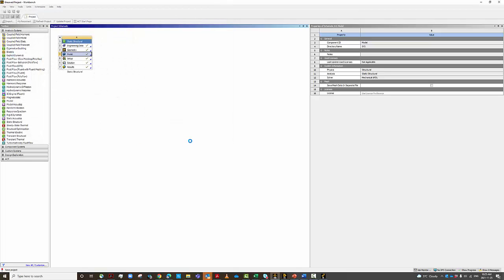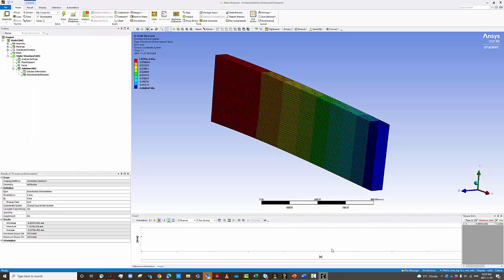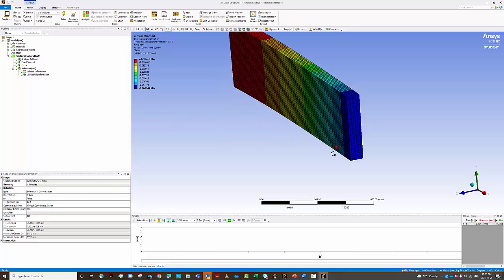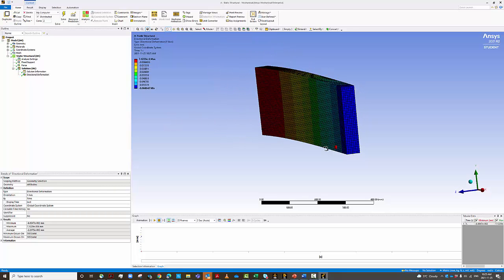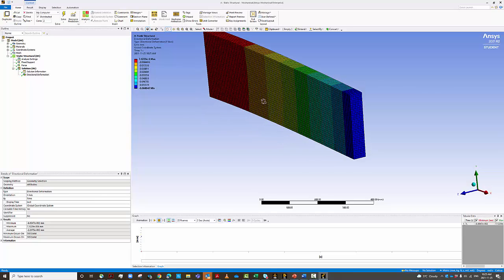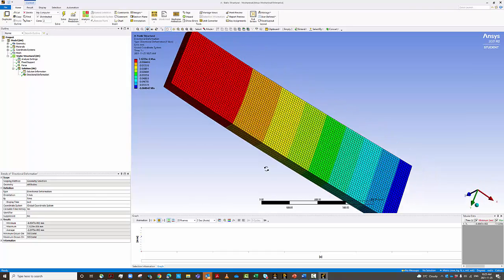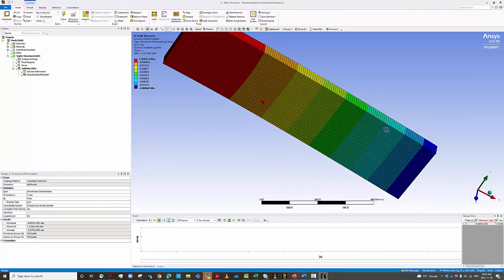right? And I'm going to host the video for you. So there is no specific criteria. What you can say is, for example, if the first 4 or 5 significant digits are the same from one mesh to another, I'm going to assume that the work is done, or when the difference is 10% or 5%. I would say 5% is a very reasonable percentage in error.